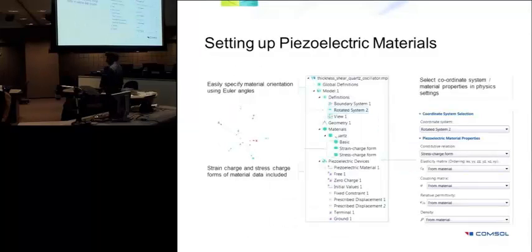The important thing to keep in mind in modeling a piezoelectric crystal, just for piezoelectrics, is to know the orientation of the crystal, or to define the material polarization. If that is not correct, your results will be shifted, or basically wrong. This one thing can change your results drastically. So you have to really define the material polarization.